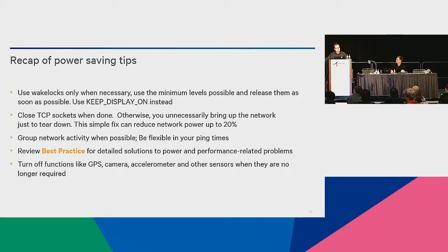Close your TCP sockets when done. Otherwise, you're going to bring up the network just to tear it down. That fix can save 20% power. Group your network activity. Be flexible in your ping times.